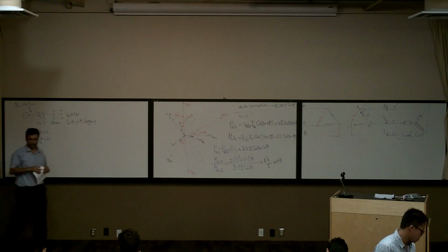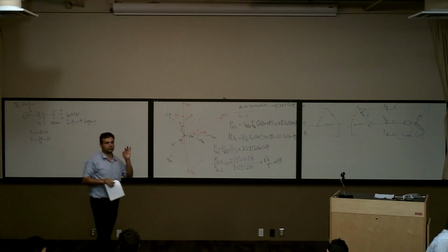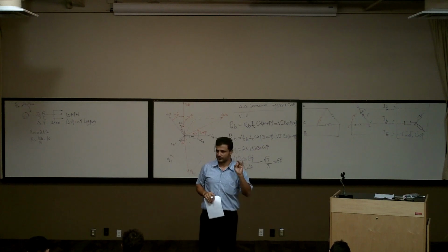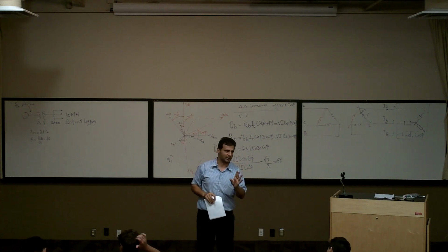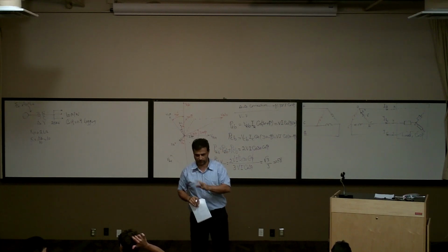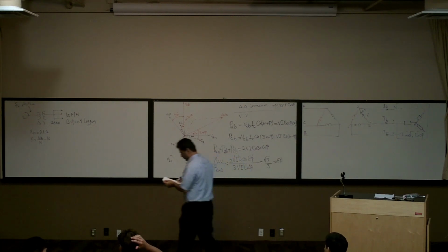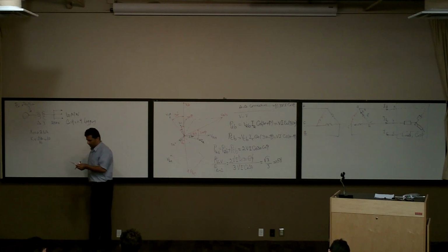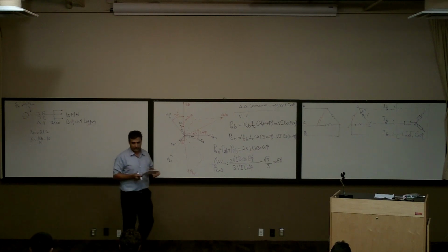Complex power of the generator. I want to calculate complex power, which means to calculate P and Q of the generator. Basically, S generator is the P generator plus j Q generator, right? It's saying calculate P and Q for the generator, how much they are. This is part A. Part B says find the phase shift between the primary and secondary voltage. That's not a big deal. Now let's do this.